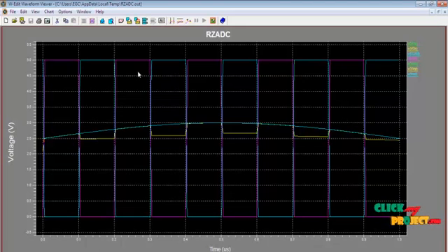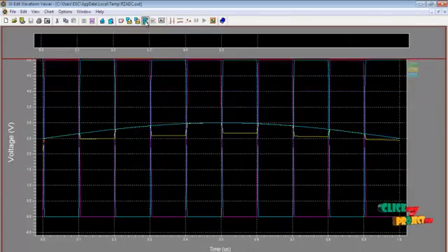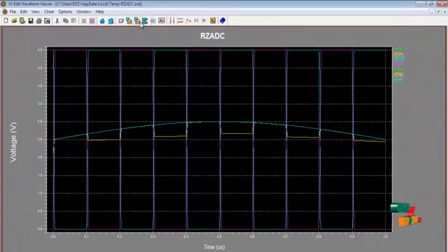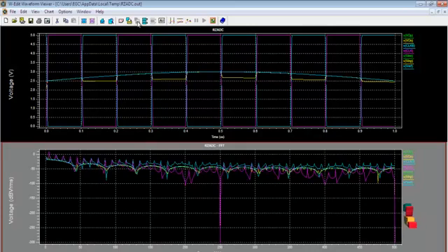In the WEdit window, first we see the input and output data of the corresponding output, and this is the normal overall output. Then we click expand chart, then the output will be separated in the format. So this is the corresponding output waveform. And next, if you want to see the frequency value and also the FFT analysis for that corresponding output, we click the FFT, then the output will be displayed in the frequency as well as the dB ranges. So this is the overall input and output waveforms.